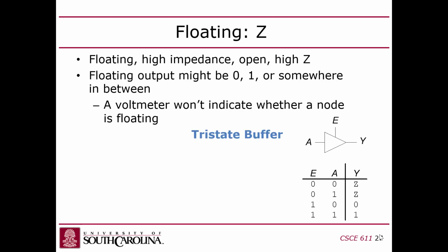Make sense? Now the question is, can you do this on an FPGA? Can you disconnect a wire on an FPGA and make it floating? Yeah, you can actually. I've never done it though. I've never needed to do it. But you can put tri-states in Verilog and you can put that on an FPGA. I've never had to build anything that required that. I might have 25 years ago and just don't remember. But I don't have any recent memory of having to do that. But you can do it.